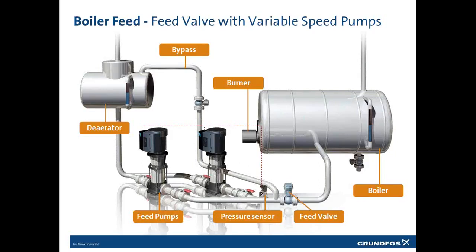When we look at a steam boiler, we should actually look at the steam boiler as a vessel containing water. And the pressure is just something that we have to overcome. The pressure is controlled by the burner in the boiler, and we don't want to have anything to do with the pressure in the boiler. That is the burner and the boiler safety system controlling that.